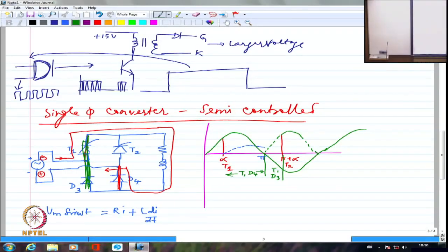See, the moment it conducts, if you forget about the fact that it is ideal, it is not ideal. It will have a resistance, definitely. And the current is flowing in this direction. That will make this slightly positive, that slightly negative. So it is forward biased by virtue of its own voltage drop.